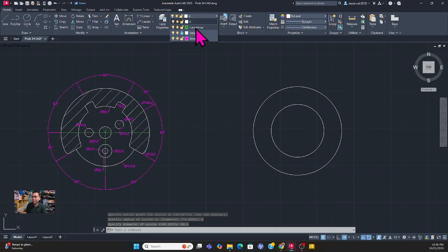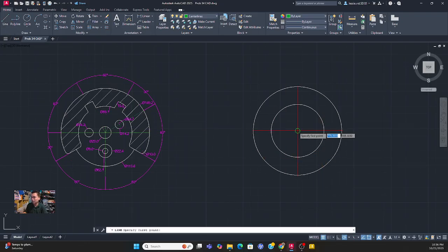Now I'm going to grab my center line real quick. I'm going to take this, track to the center, go to the edge, and go all the way to the right. Hit escape. For some reason, my construction line did not register the center line. I'm going to just have to do it by hand. All right, there we are. And then I'm also going to do my center line this way. I have no idea what's going on here with my center line. Could be a glitch, could be something going on, not sure. All right, there we are.